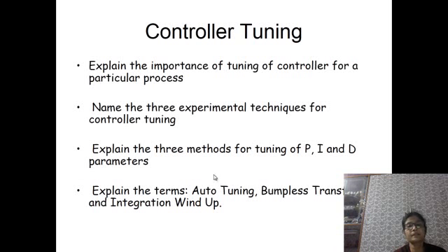For integral action, the controller parameter is integral action time Ti, and for derivative action, derivative action time Td, or the inverses, that is the reset rate and derivative action constant, Ki and Kd